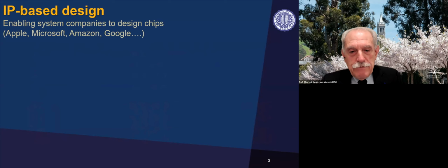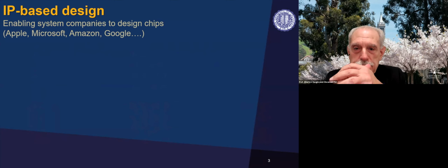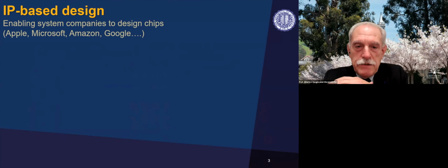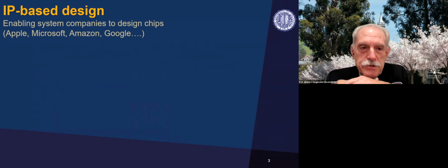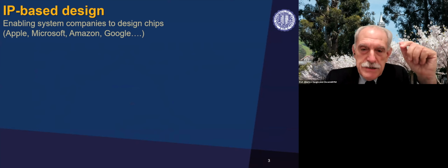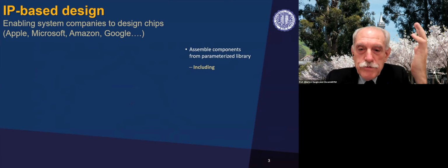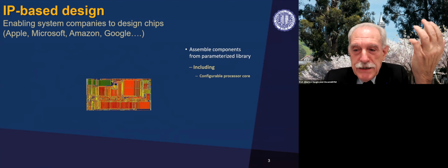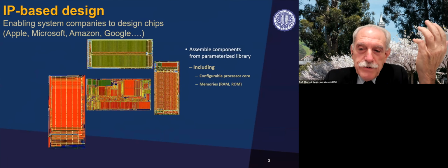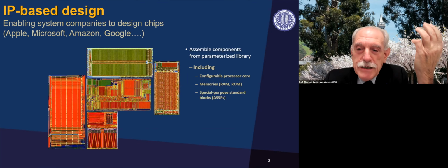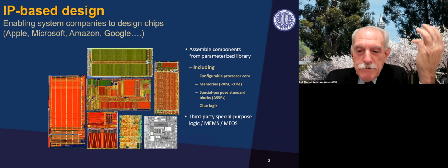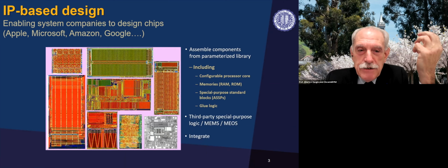Well, if you look at one of the key elements of the methodology that has been used in the integrated circuit domain, it is IP-based design. What does that mean? It means that you are building complex chips by including components that have been pre-designed and are part of the library. So you can have a configurable processor core, you add memories of various type and kind, special purpose standard blocks, and then you have glue logic, and then you put it all together with MEMS and other interfaces, and off you go, you have a product.